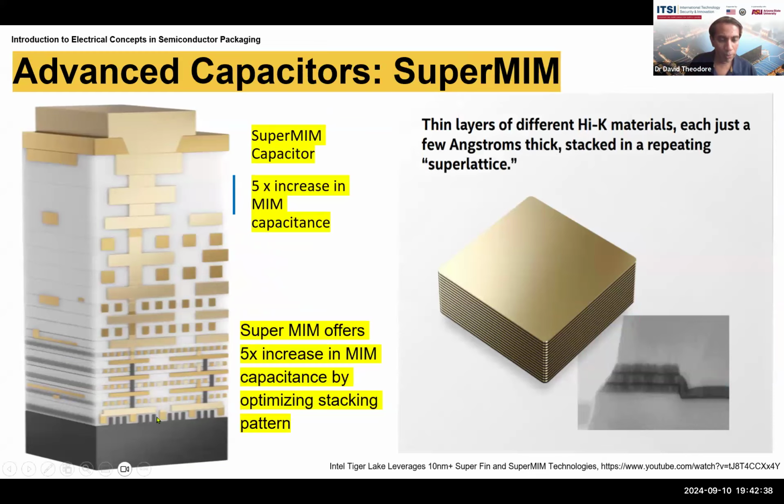So the silicon chip is down here. So you got the die. So this is silicon down here, the die, and then you have the transistors and so on. And above this, you got the interconnect layers. So the golden lines, the squares are basically lines that are coming out of that plane, which typically are copper lines or something of that sort, where signals or power is being brought down here. You can see there's a metal connection going down here, right? Ultimately to the devices. Now, the longer lines here can be a line that's going parallel to this face.